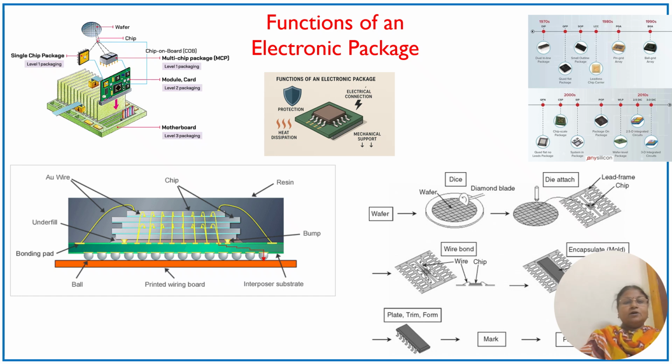If these leads are going to be inserted by means of a through-hole technology or by means of a surface mounting part, that is another part of your IC. Now coming to the design, single chip. First let me take a single chip, because the concept is understood only from this single chip packaging, where from a wafer we just make an IC.